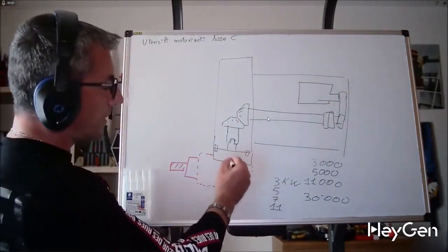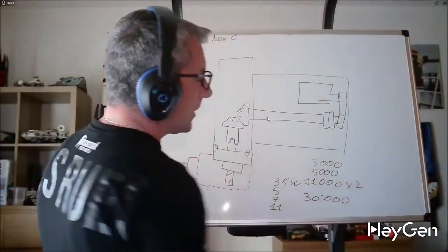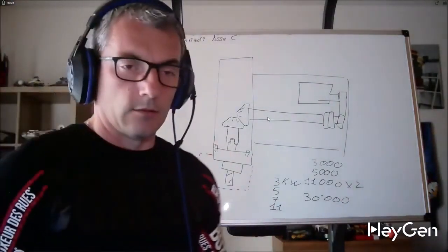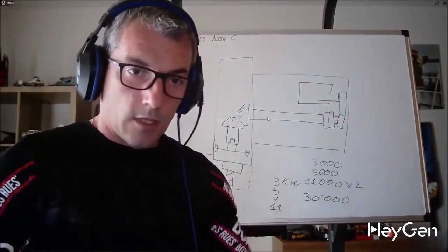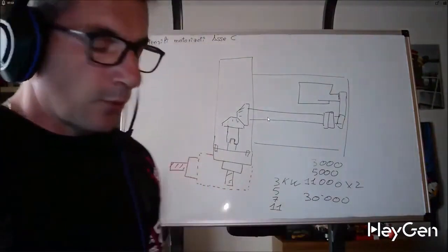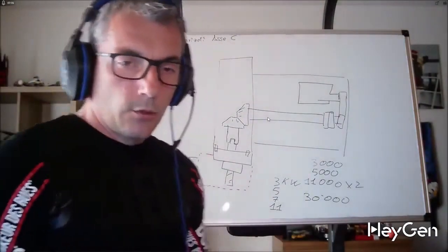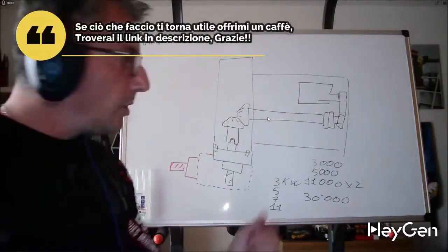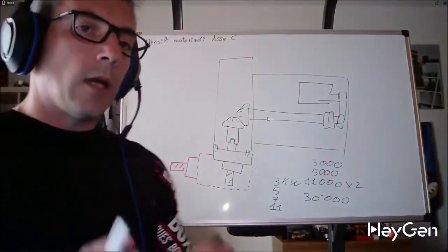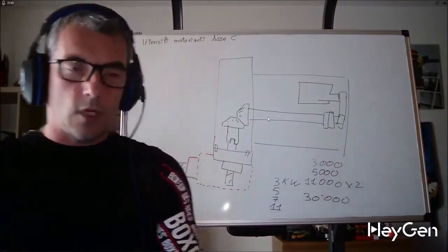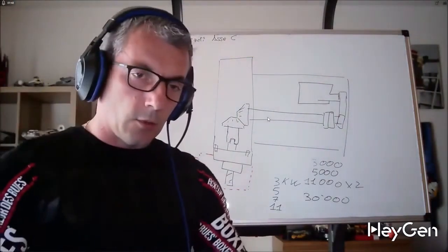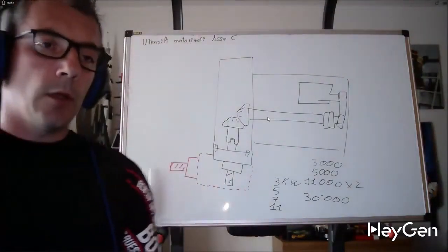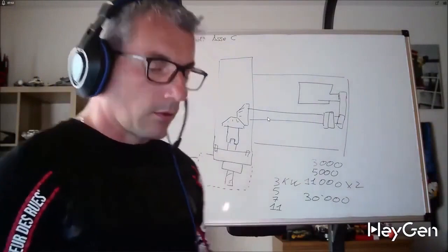We even have powered tools with a variator that doubles the RPM, but it's not the same as a machining center. So it might seem like I'm just bashing these powered tools, but that's not the case. I'm simply presenting you with their limitations. When do the limitations come into play? When we have to decide how and whether to work on a part on a lathe 100%, including offset holes, or to split the two operations between a lathe and a machining center.